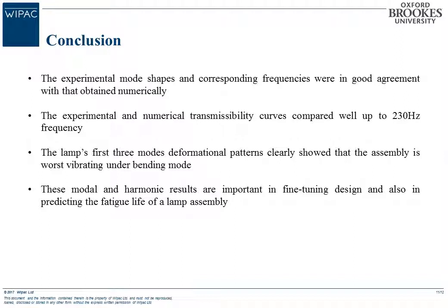Conclusion. The experimental mode shapes and corresponding frequencies were in good agreement with data obtained numerically. The experimental and numerical transmissibility curves compared well up to 230 Hz frequency. The lamp's first three modes' deformational patterns clearly showed that the assembly was vibrating under bending mode. These modal and harmonic results are important in fine-tuning design and also in predicting the fatigue life of a lamp assembly.